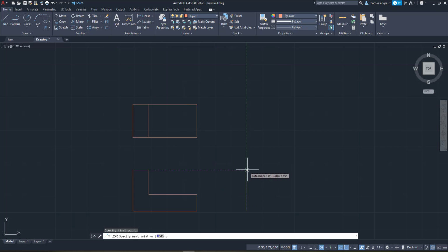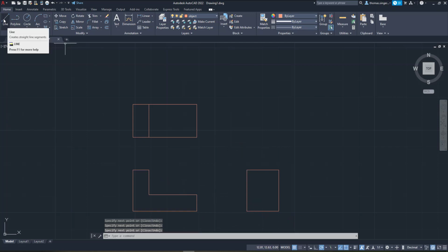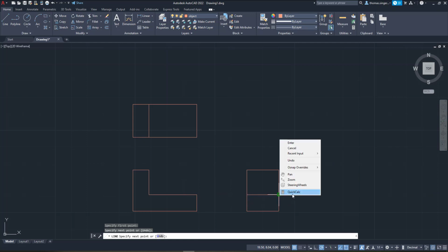Interesting, we don't even have to type. Now we know that it's 1 inch in depth because we just drew the same top view. We can highlight the bottom corner, bring it across, line it up so it's perfectly perpendicular, right mouse click and choose enter. And lastly, I'm going to go back up and choose the line command, highlight the edge, bring it straight across, and bring this straight across.